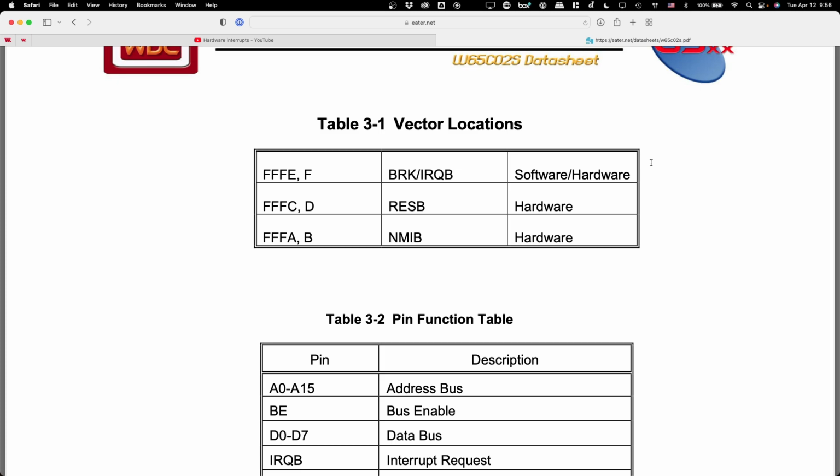There's the interrupt request, which doesn't have to be dealt with immediately, and there's the non-maskable interrupt that must be dealt with immediately no matter what. Think of non-maskable interrupts as absolute showstoppers that under all circumstances you must deal with right this instant, and regular interrupts for anything that's not quite that important.